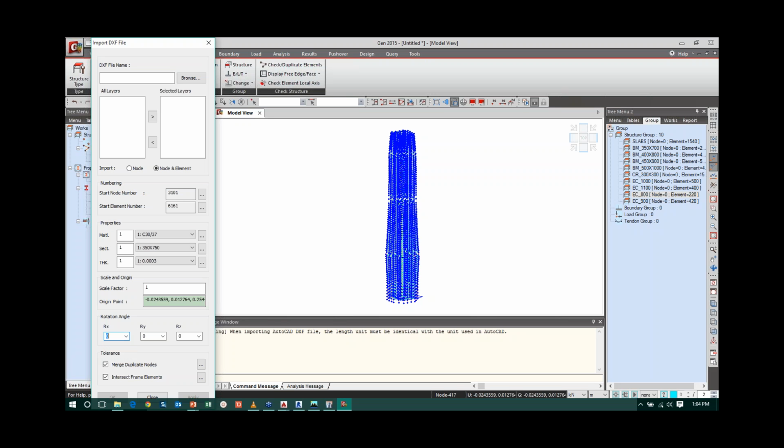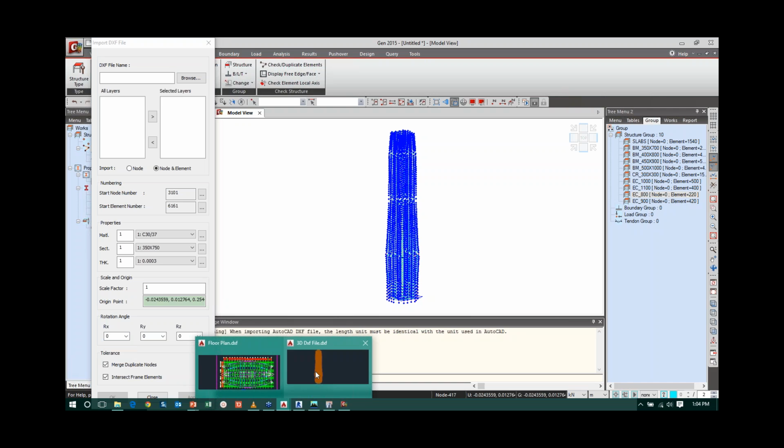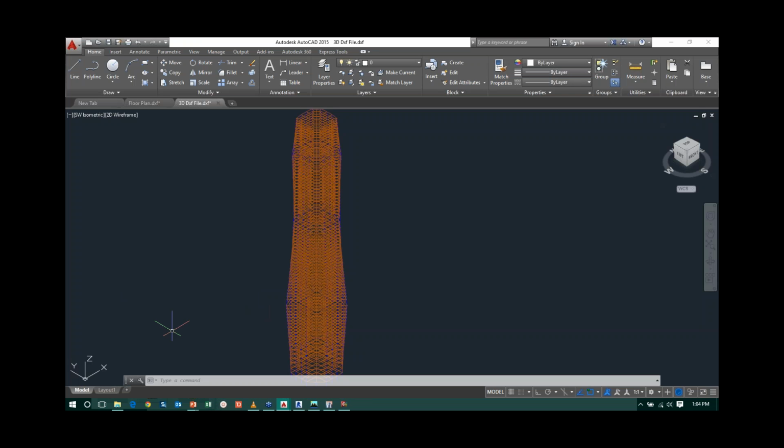And the next question is, how can we believe this is the critical axis? Sir, critical axis, actually there is no right way to say, but you need to check both. You need to first check the AutoCAD drawing, what is the plane, in which plane your floors are lying in the AutoCAD drawing. So either it is in XY plane or XZ plane. So that gives you an idea along which axis we need to rotate. So for example, if it is in XY plane, in MIDAS also the horizontal plane is XY plane. So there is no need for rotation.